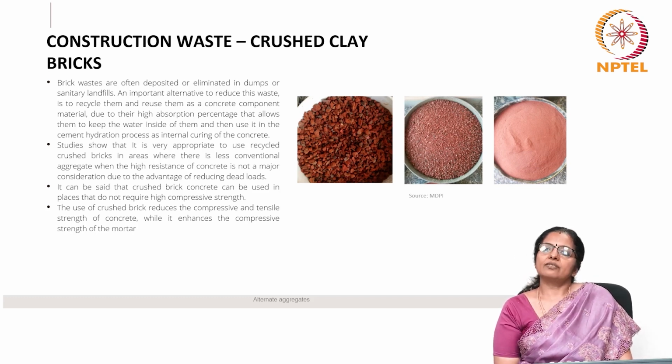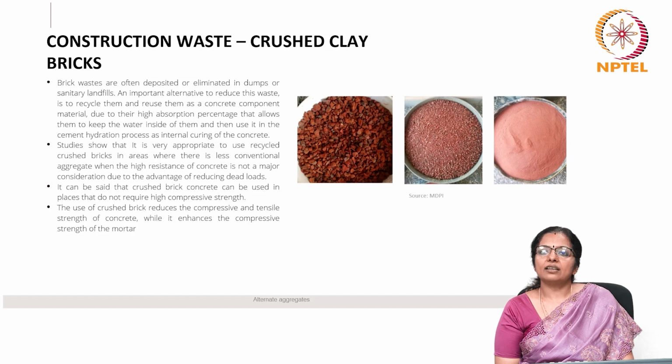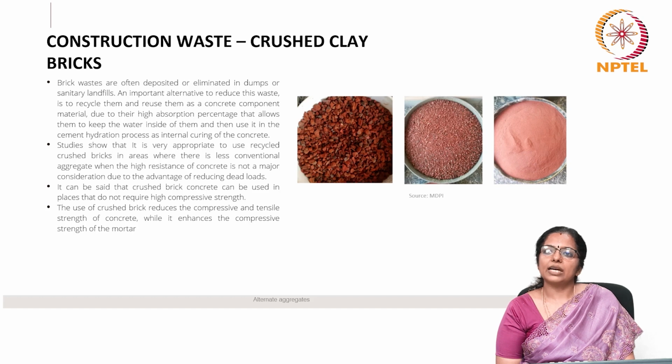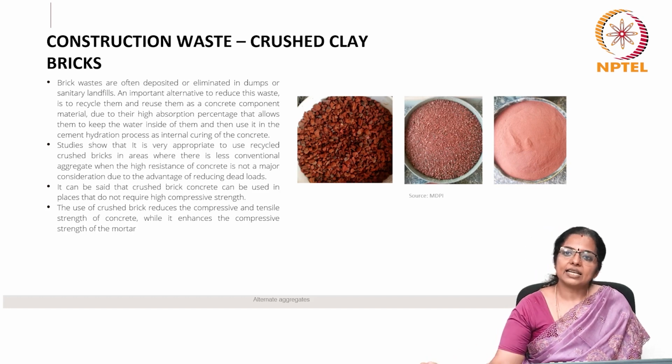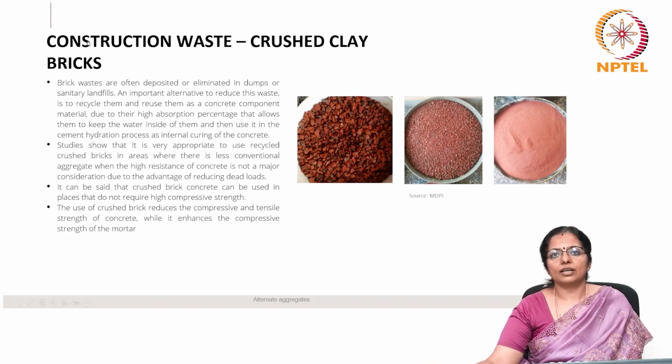Studies show that it is very appropriate to use recycled crushed bricks in areas where there is less conventional aggregate, when the high resistance of concrete is not a major consideration, due to the advantage of reducing dead loads. It can be said that crushed brick concrete can be used in places that do not require high compressive strength. The use of crushed brick reduces the compressive and tensile strength of concrete while it enhances the compressive strength of mortar.